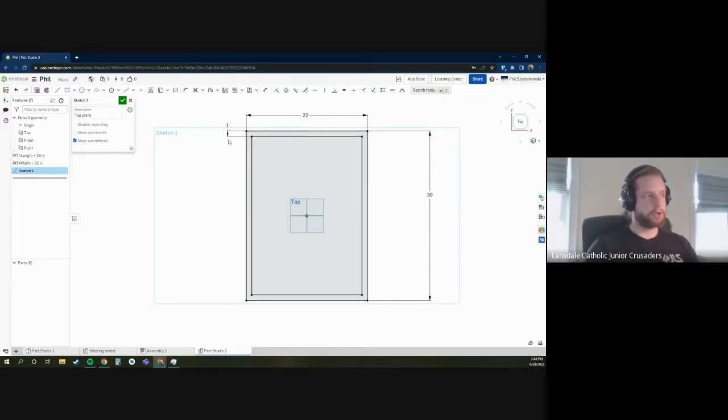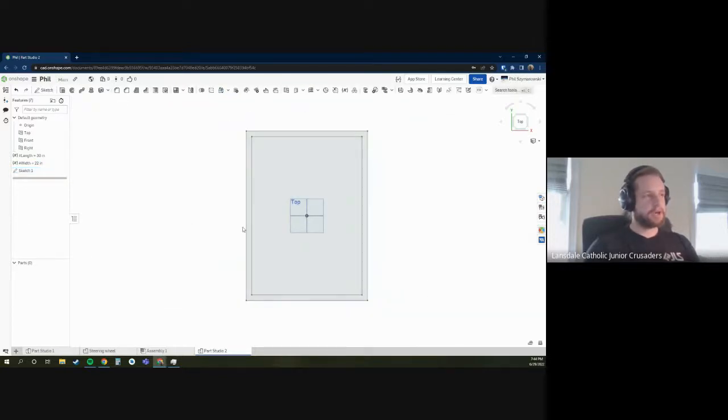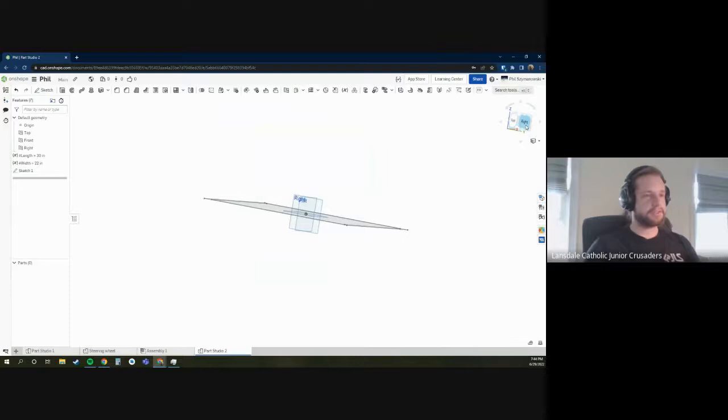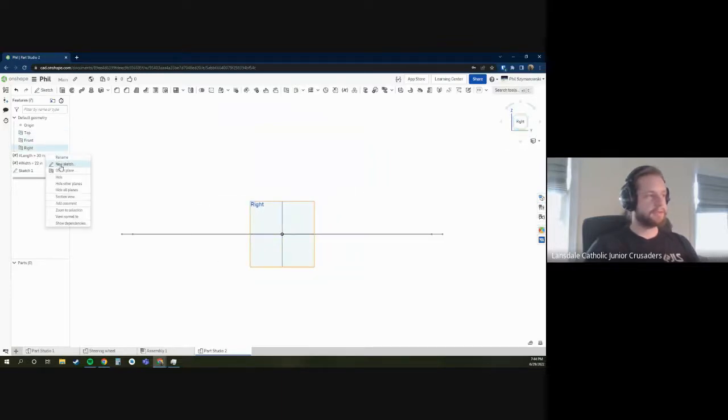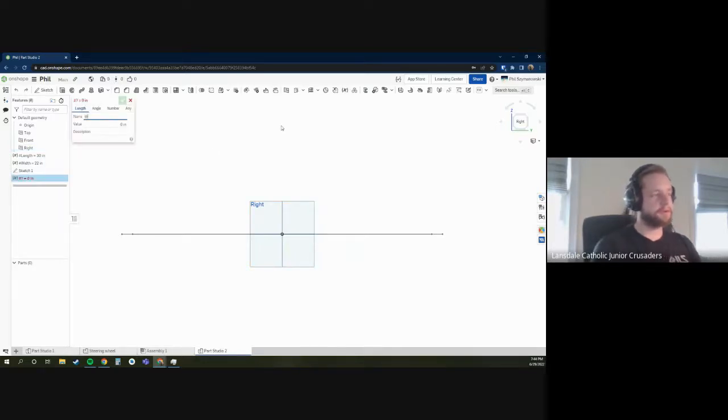All right, cool. So I'm going to start off with this as a frame, and we can always change it. I'm also going to start a sketch from the side. We're going to make a sketch on the right plane. But before that, I'm going to make one more variable, called wheel D. I'm going to call this the diameter of the wheel. You'll see how we utilize this in a second. And let's set it to 3 inches to start with.